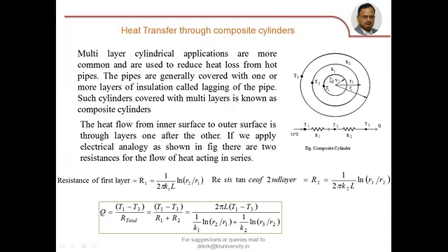First heat has to flow through layer 1 and then it will flow through layer 2. So the resistances are acting in series. Resistance of insulation 1, say R1. Resistance of insulation 2 is say R2. The temperature at the nodal point before this is T1, at the end of the second resistance the temperature is T3, and at the interface it is T2. Heat flowing through each resistance is say Q.